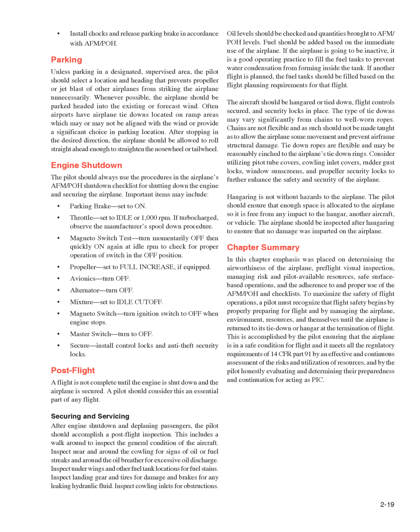Fuel should be added based on the immediate use of the airplane. If the airplane is going to be inactive, it is a good operating practice to fill the fuel tanks to prevent water condensation from forming inside the tank. If another flight is planned, the fuel tanks should be filled based on the flight planning requirements for that flight.